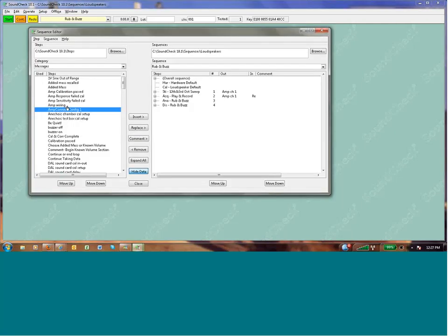Okay, so now that I have my AmpConnect added to my hardware step, I can now communicate with it directly in my sequence. So just like all of our other pieces of hardware, things like RS-232 or GPIB, digital I/O, the way we communicate with AmpConnect is through a message step. If you've seen some of our previous webinars, maybe you saw our message step webinar that went through how to do all that. Well, now we have a new section in the message step. So let me add this default step into my sequence.